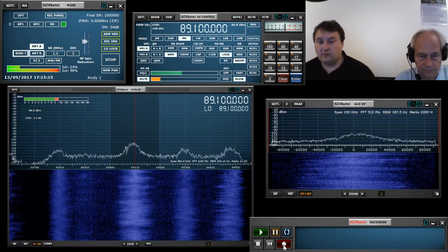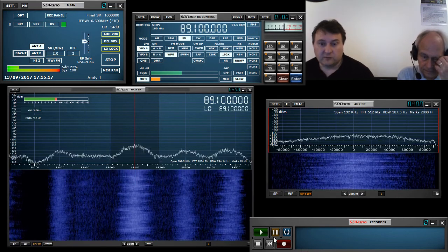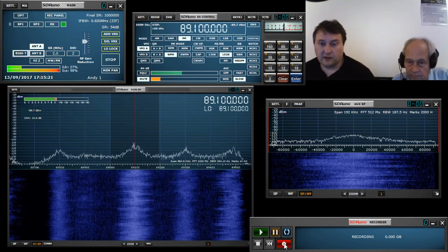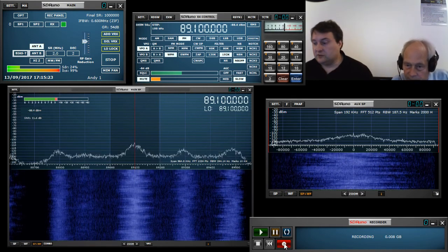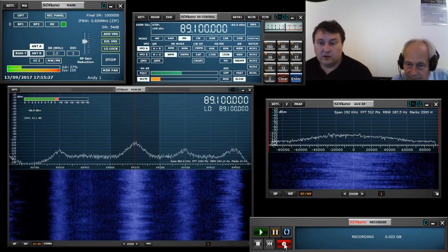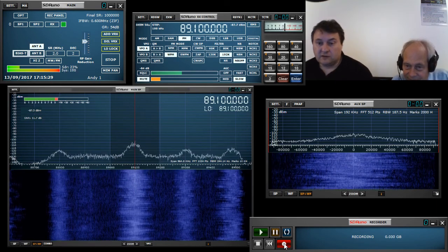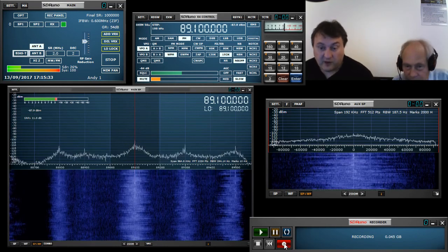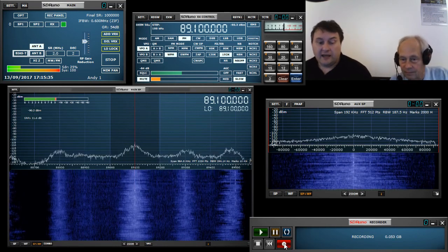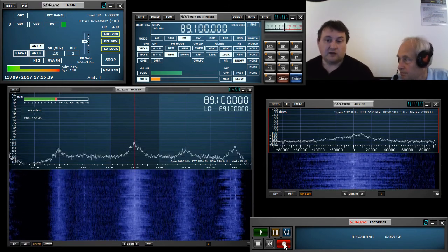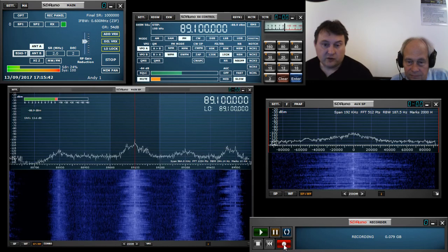So I'm only viewing 1 megahertz of spectrum here, and so when I press record here, it's now going to start to, I don't know if you can see those values, but we're at 23 megabytes, 30 megabytes. Wow. It's going up at a rate of about 4 megabytes a second. And so what's happening is it's recording the entire IQ bandwidth. So I can now stop this.